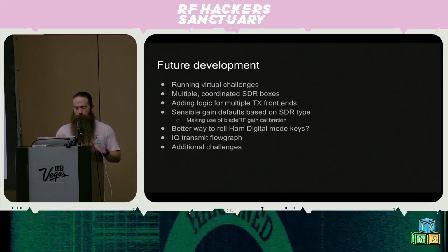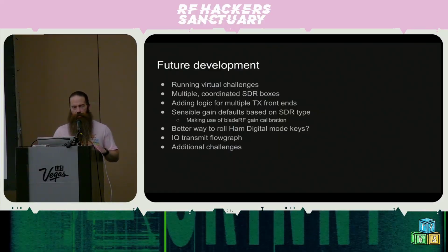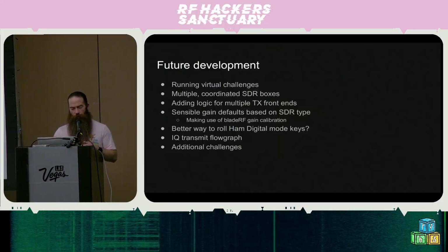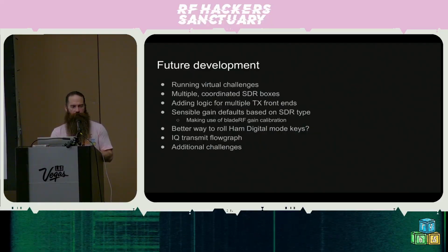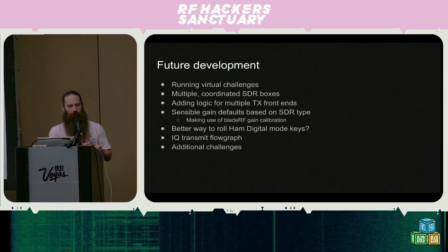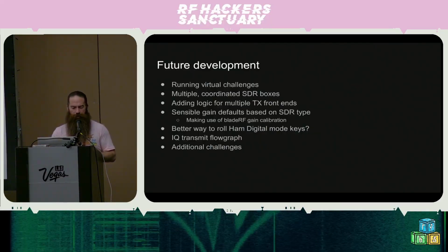We need to make sure that we have consistent gain settings, at least across all the challenges for all the blades, but also having sensible gain for HackRF. So if I know I'm transmitting from a HackRF, saying I know this is a reasonable setting for that, and setting that automatically would be really nice.